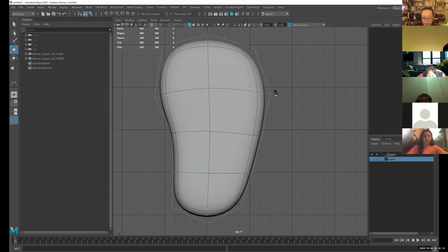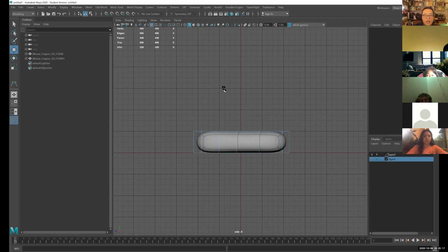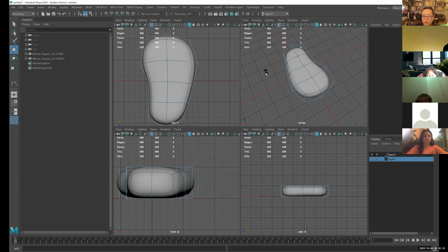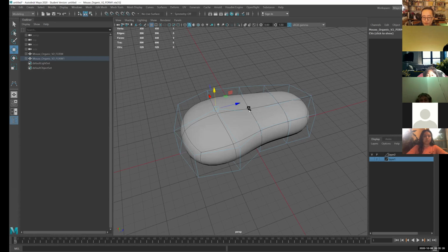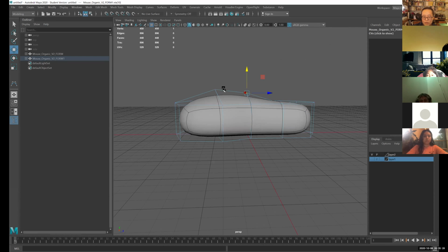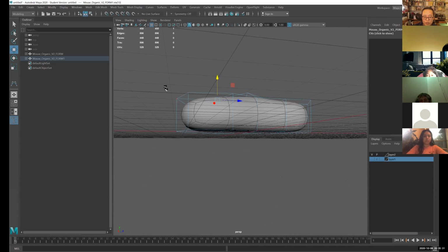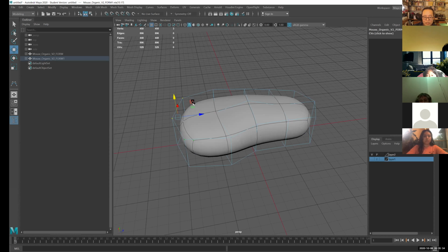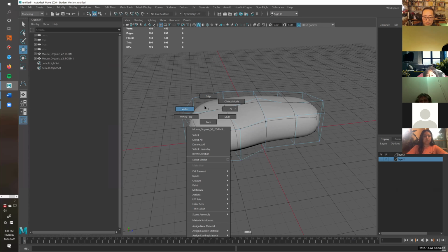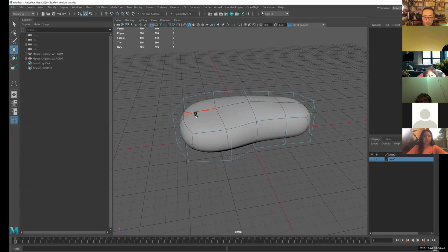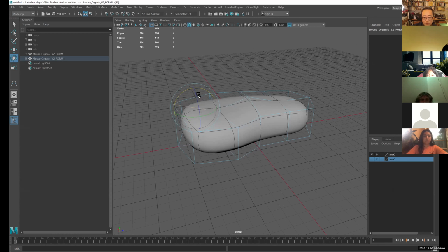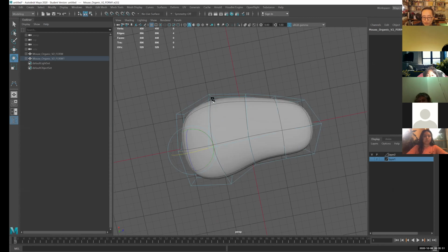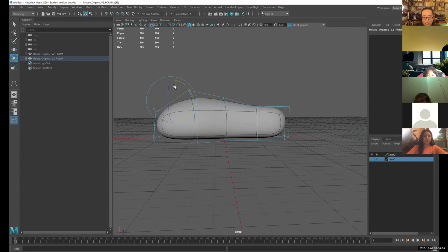And then let's go to another view. I guess I can work in the perspective window a little bit. So let's select the vertices and move them around. Okay. Actually, is this lower in the front? Maybe it's a little lower in the front. So let's select some of these guys. You can always select also the edge and faces. Those are options too. So that's a whole edge here. So you can move, or you can also rotate. Press E and rotate. So you can get gestures and angles that way as well. Okay. So yeah. All right.